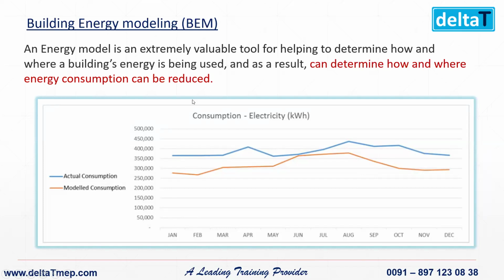This is the best part. When I do the calculation, I might find that in the lighting system more power is consumed, so I might use different types of lighting fixtures. And in the air conditioning system, if I put non-central AC, I get a lot of power consumption. The initial cost is less, but the running cost is high. If you take central AC, the initial cost might be high, but the running cost might be less. So with this we can analyze.